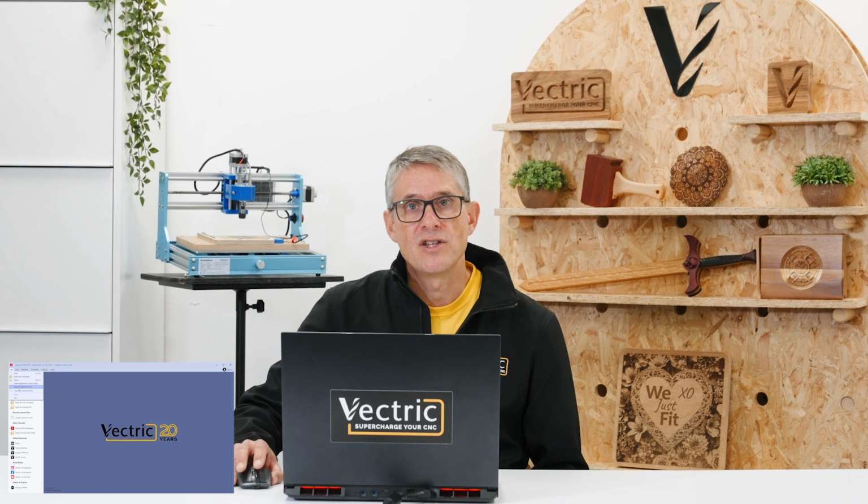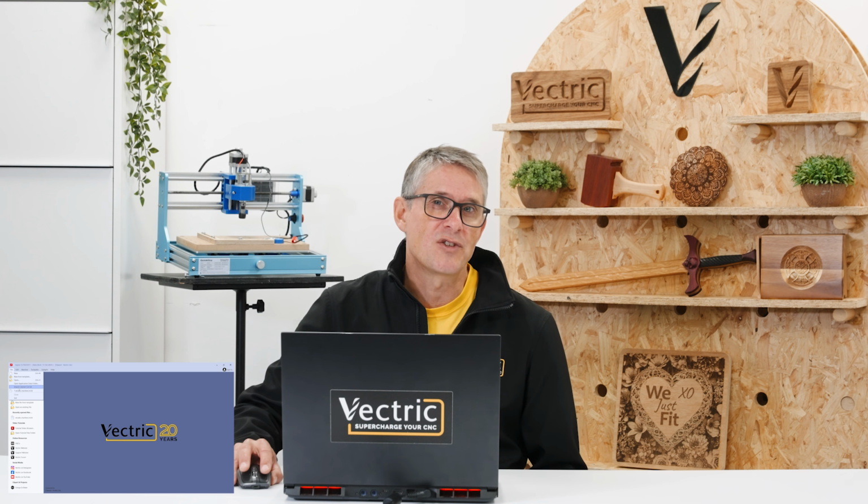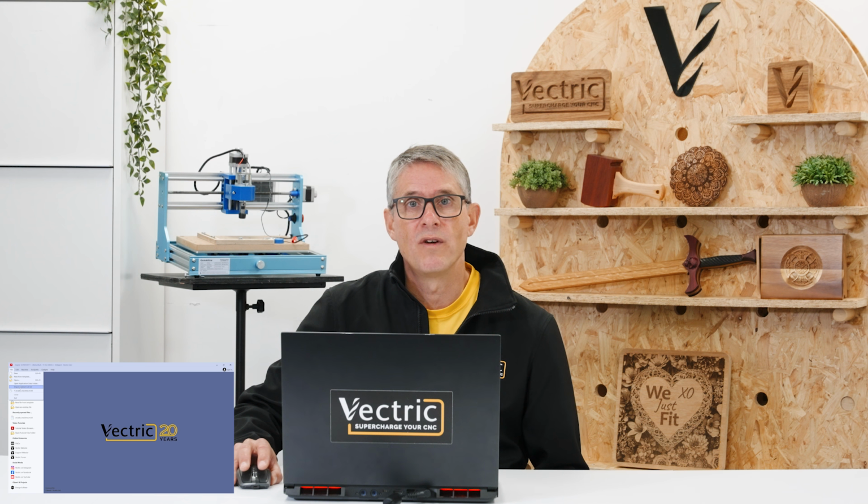These design packages typically generate a set of toolpaths built off a DXF master file, but you have to, in your particular design, generate how many of these things you're going to require. And then we've always offered a service internally in our higher end products of VCarve Pro and Cut2D Pro of nesting those parts automatically. And we've had a gadget which has kind of helped. If you could get everything into one folder, we had a gadget which would process through those folders.